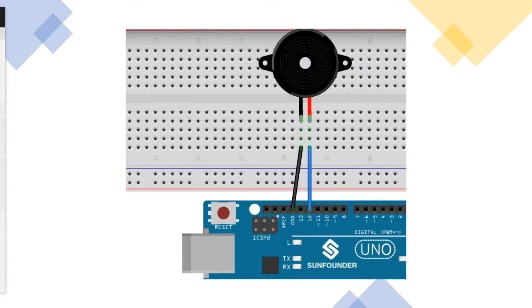So you are well equipped when you know about the buzzer and the tone. And remember, we were talking about the function of no tone, and then the function of just high and low. We are very conversant with high for turning the actuators on. Any output device can be turned on by putting high, and turned off by putting low: digital write low, and digital write high. Those are the major ways you can turn these modules, gadgets or devices, basically the actuators, on and off.